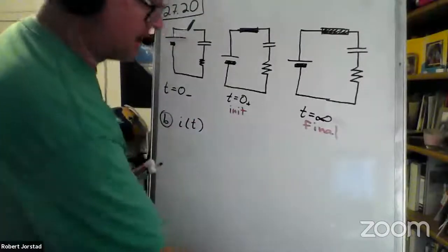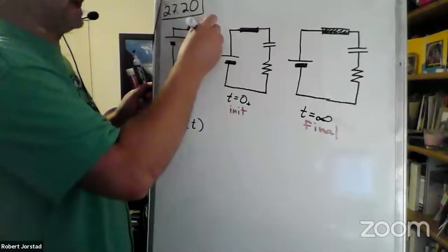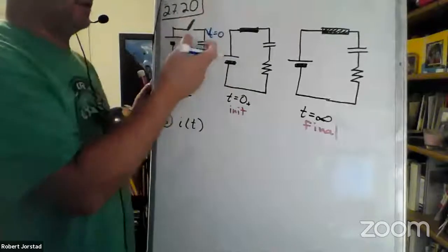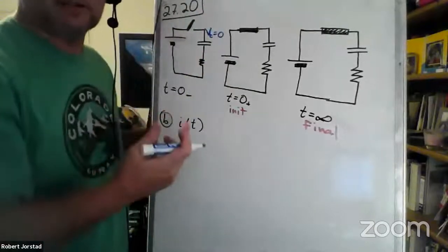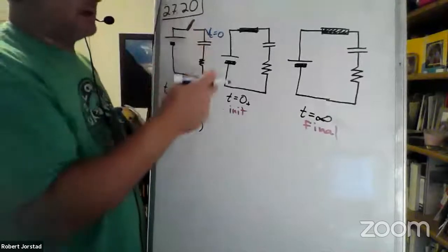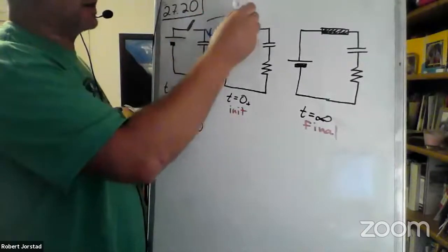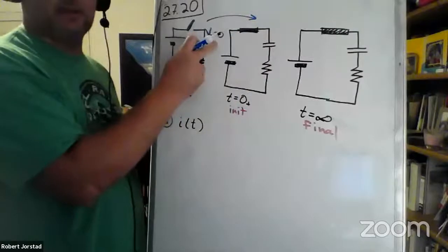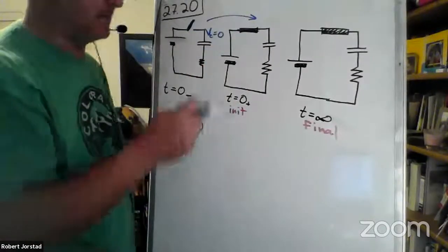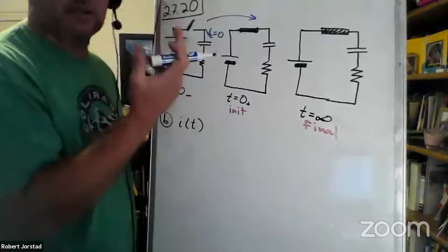Okay. So in this case, we know that the voltage of the capacitor is initially 0. For room purposes only, I'm not writing the delta V just because it's already so small. Now what do I know? I know that is what carries over, and I knew this because the problem told me it's initially open for a long time. That tells me there's no charge on the capacitor initially.